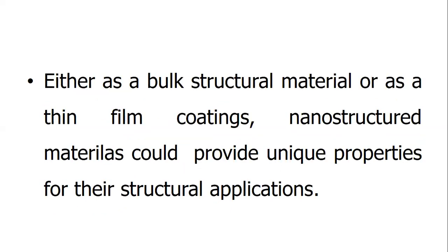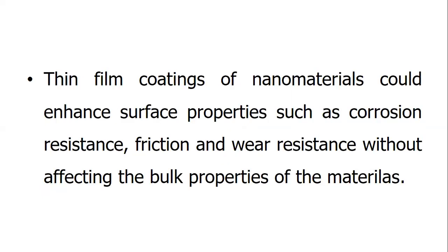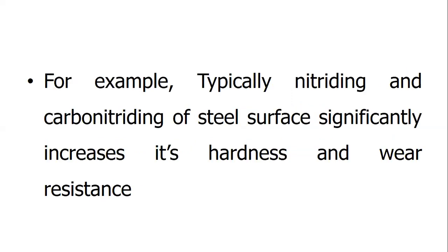Either as bulk structural materials or as thin film coatings, nanostructured materials could provide unique properties for structural applications. Thin film coatings of nanomaterials could enhance surface properties such as corrosion resistance, friction, and wear resistance without affecting the bulk properties of the materials.